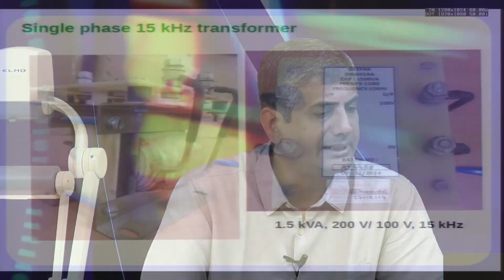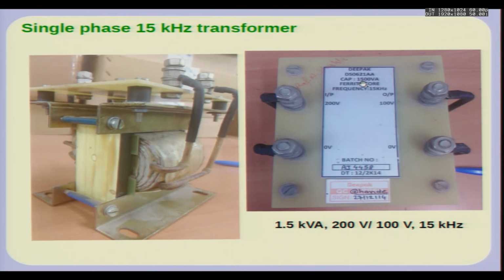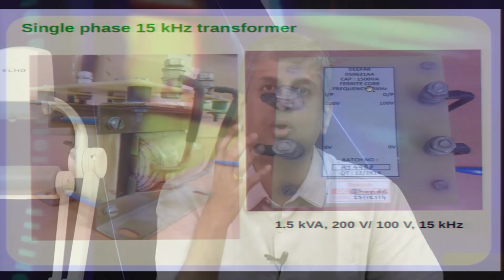For a high frequency transformer, we use ferrite cores because the eddy current in fact becomes very high. So, it is best to use a core material which is non-conducting. The earlier material was steel, but here we have a ferrite core which has very low conductivity. So, eddy currents are negligible, and this is required for high frequency transformers where the rates of change of flux are high. So, the chances of having more eddy current losses in the core is much higher.